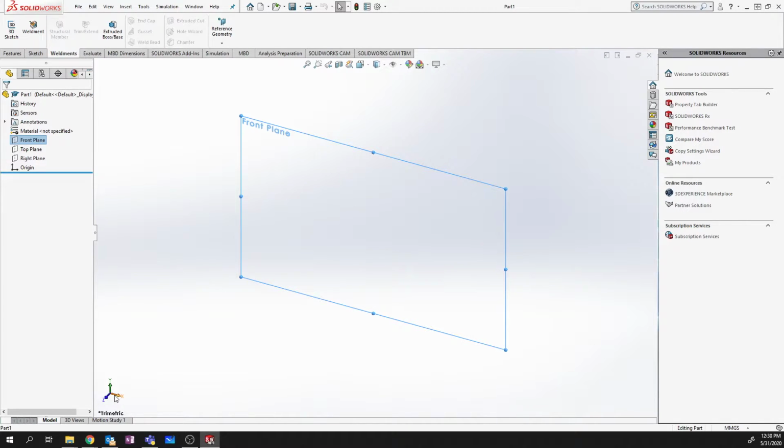If you're facing the robot, X positive is kind of towards you. So the door on the work cell will actually be at the most positive location in the X of your work cell. So this is something that we want to keep in mind. Depending on what it is that you're doing, this may be different, but that's the basis that we're going to go off of for setting up this particular configuration.